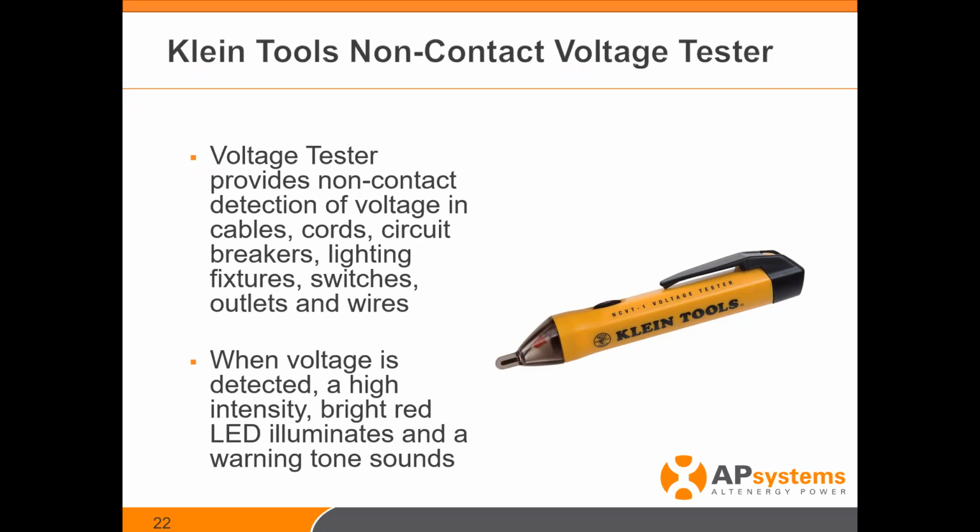But for a quick test, if you open the box up and you want to verify the breaker, for example, we have customers call up and say, you know, it's not working. I want to be able to test this. And I said, well, check the breaker. Verify that the breaker isn't bad. And, you know, we're all in the industry, and breakers are pretty reliable, but I have seen them go bad. This is a great way just to be able to tap on each of the legs and verify that there's voltage or not coming out of there. Quick, easy, audible, and a visual is an LED flashing light that actually indicates to you that there's voltage. So nice product again, very easy, something you use for troubleshooting. It's a must.